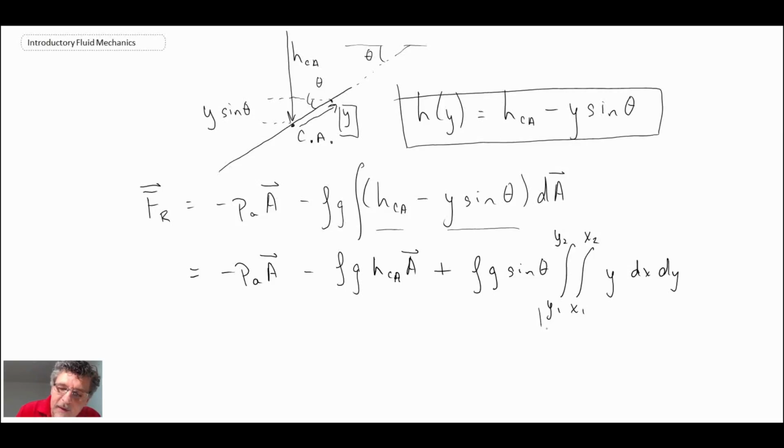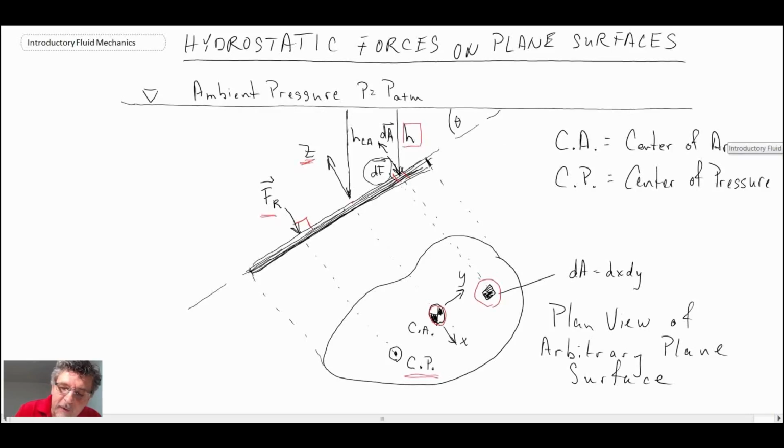Now, this is an integral that is rather well known, and what that refers to is the center of area for the plate itself. So that would be the center of area, but remember, we've defined our coordinate system. Let's go back to our schematic. We define the coordinate system to be about the center of area itself.